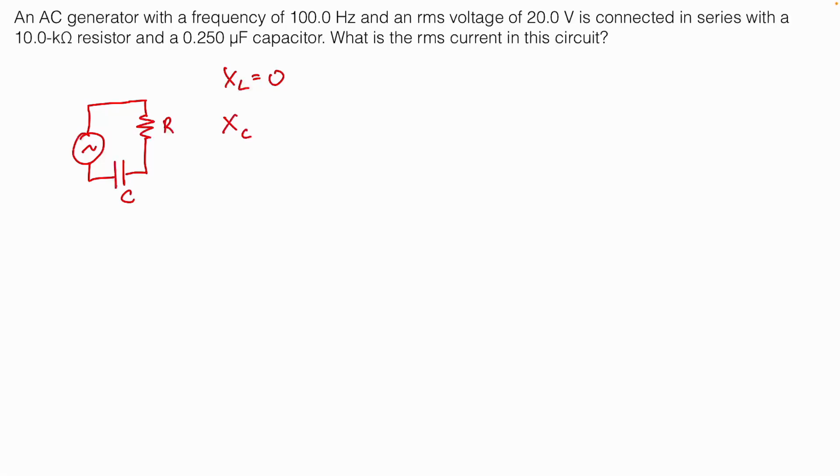my reactive capacitance is. And do you have any notes? What's the reactive capacitance equation? 1 over omega C, right? Okay. So now we need to find omega. Oh dear. What did they give me up here? 100 hertz. Is hertz omega? No. Omega is equal to 2 pi f, isn't it? So I take 2 times pi, and then I multiply by 100, and I get 200 pi.